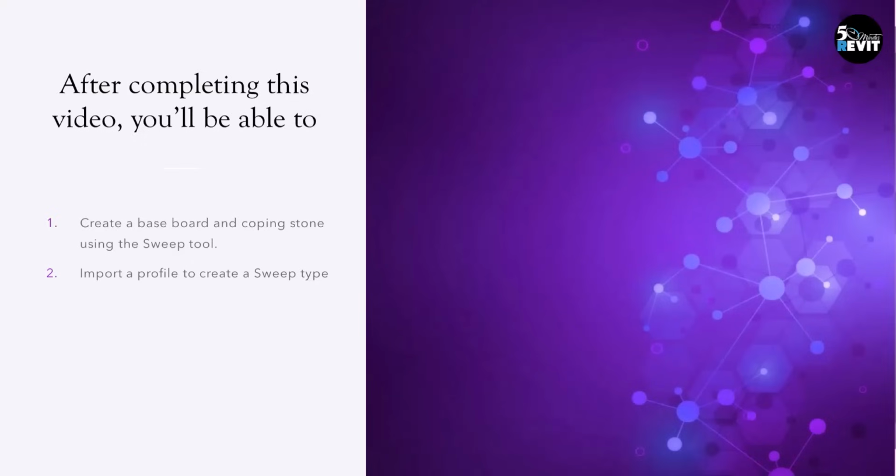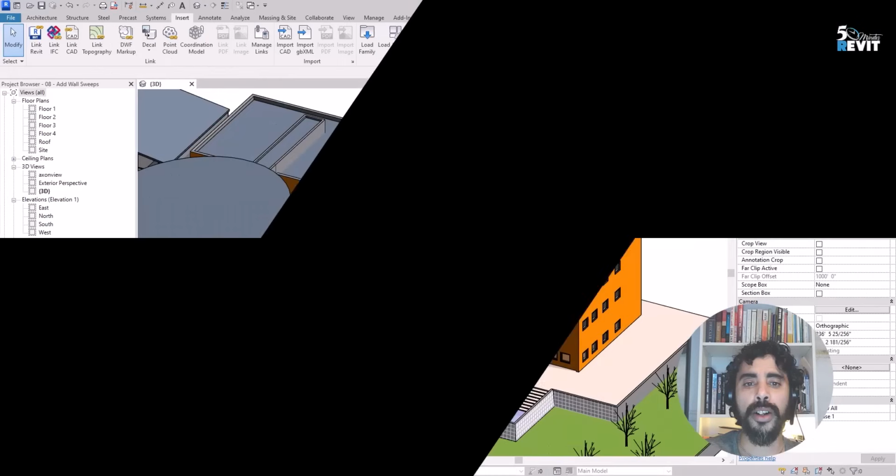In this video, we see how to create a base, bold, and parapet coping using the wall sweep tool. And we also see how to import a profile family to create a new sweep type. The sweep tool is used to create components that are hosted along the length of the wall. A profile family is used to define the two-dimensional cross section, which is then extruded with the sweep tool. The sweep tool is useful for creating components such as a baseboard, cornice or coping stone.